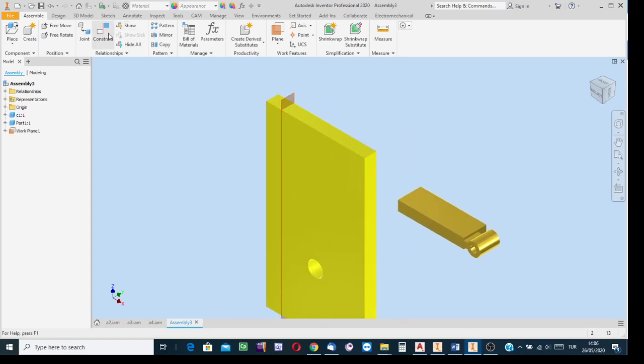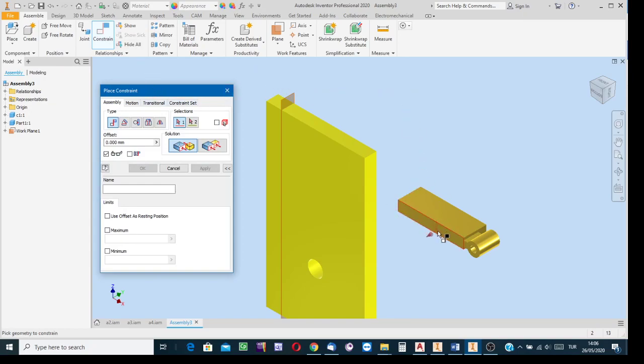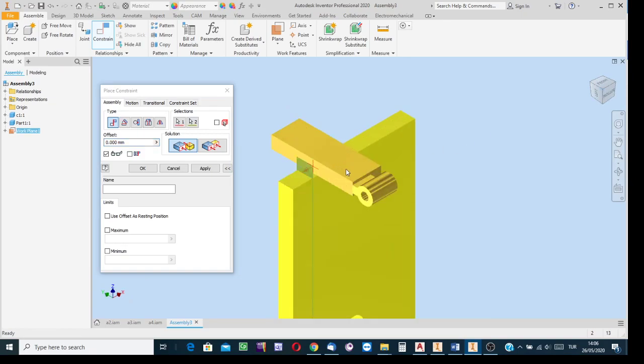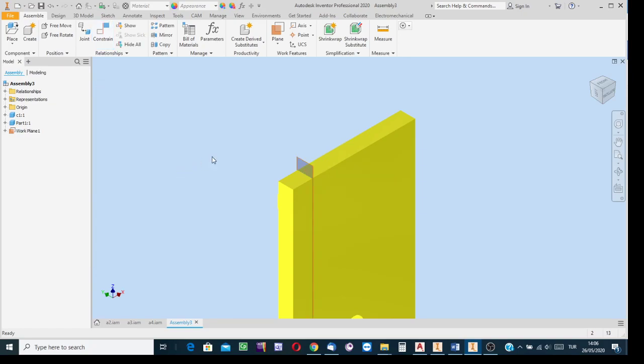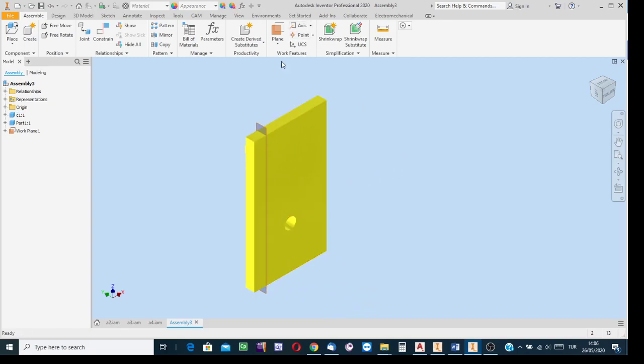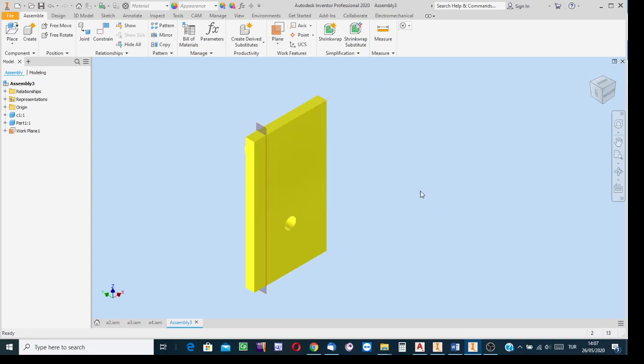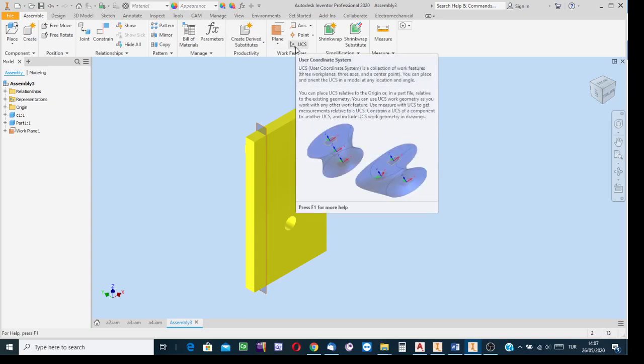And then, mating issue. Instead of mating this surface onto that one, onto this one, etc., say that the surface of this component is to be mated over here. Say it is an imaginary surface, but as if it were the surface of this component, it can be indicated. Indicate the surface. You see now indicated surfaces are in relation. A useful technique. While using work planes, you can position one component with respect to the other. Keep in mind, those can be invoked dropping the list and selecting. These are the work plane invoking options.